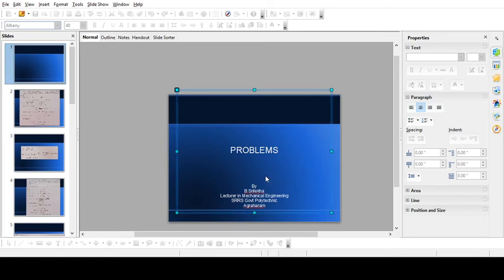Next, stress along the z direction, σ_z is 4 meganewtons by area, that is nothing but 4 into 10 to the power of 6 by area. How much? 250 into 100. So that is what we have written. For the first one, along the length 250, the cross sectional area is 50 by 100. Along the y direction it is 250 by 50, and along the z direction it is 250 by 100.